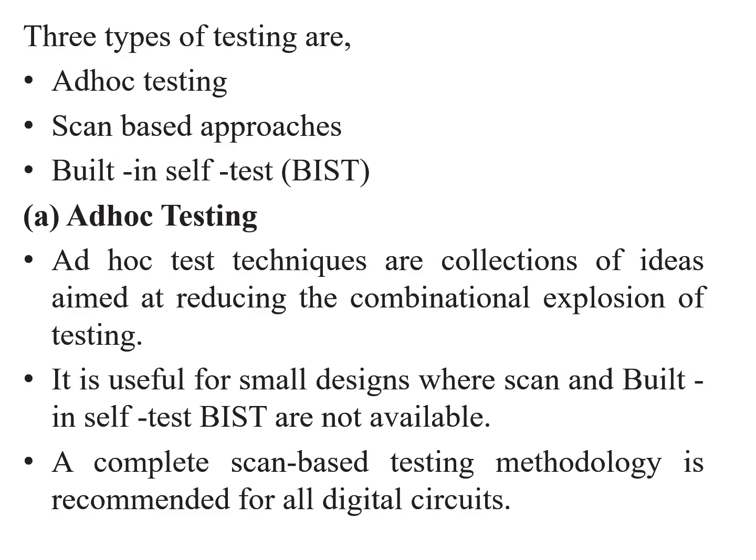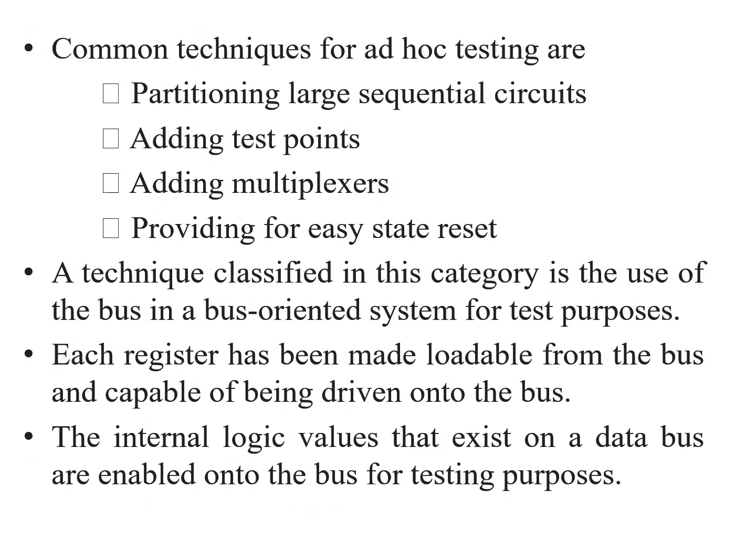Ad hoc testing. Ad hoc test techniques are collections of ideas aimed at reducing the combinational explosion of testing. It is useful for smaller designs where scan-based approaches as well as built-in self-test are not available. A complete scan-based testing methodology is recommended for all digital circuits. Common techniques for ad hoc testing are partitioning large sequential circuits, adding test points, adding multiplexers, as well as providing for easy state reset.